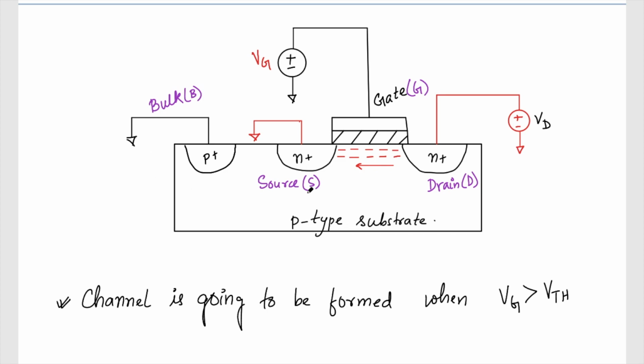Now if you see here, this has multiple PN junctions. So I have this E, P, and N, P, and N. And what I want to make sure is that these PN junctions are never forward biased. These PN junctions should always be reverse biased. That's why this bulk potential has to be always connected to the lowest potential in a circuit, so that any of the PN junctions that I have or that I will have in future should not be in forward bias condition. This can only be achieved if I connect this bulk potential at the lowest potential.